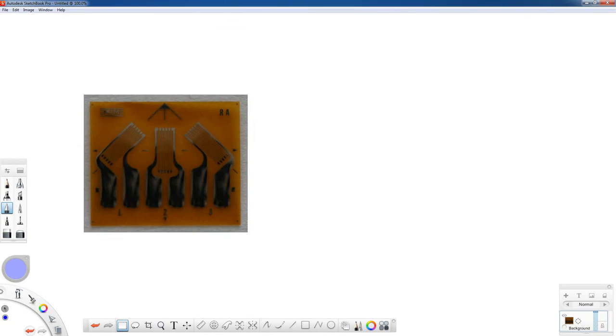Okay, so this is a picture of a strain gauge rosette, and this one has not been put down on a component yet, just a picture of the gauge itself. You notice the three strain gauges that make up this rosette. Now, the way this is oriented, here's the coordinate system. So this would be like the x-axis going this way. This would be the y-axis this way, and this would be the 45-degree bisecting gauge.